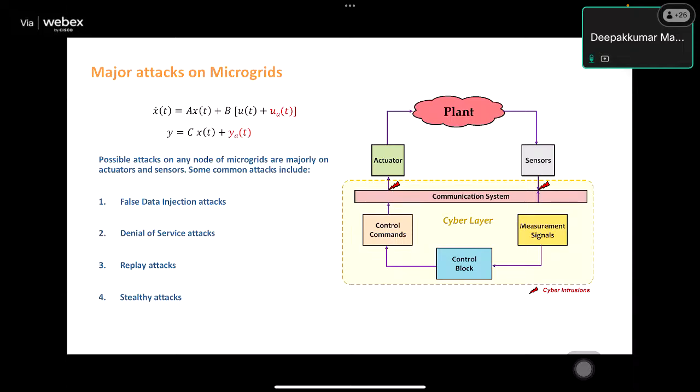If you consider a system described as a linear time invariant system, this is one way in which you can describe it. Many converters are actually nonlinear. In fact, they are bilinear systems, so they are highly nonlinear in nature. But you can always linearize and get this particular form of system. Like obtaining a small signal model for many power converters, that small signal model is essentially represented as an LTI system after linearization.